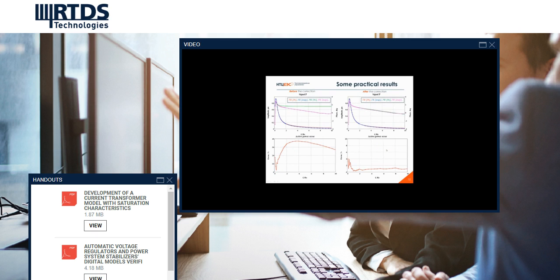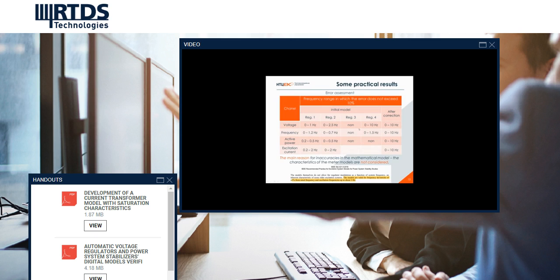The same results for the channel of active power. So here is the manufacturer model, experiment results, error, and these results after correction. In our experience, the initial manufacturer models of AVR and PSS remain correct up to a frequency of 0.5 or 1 Hertz.